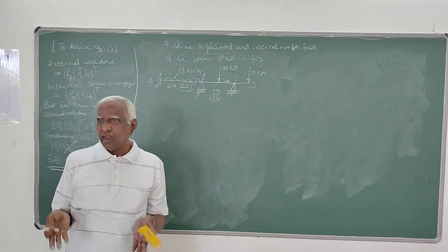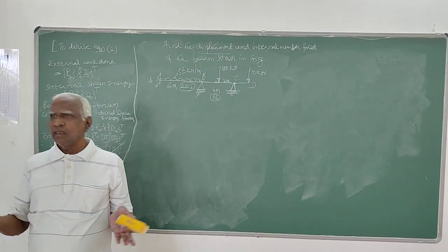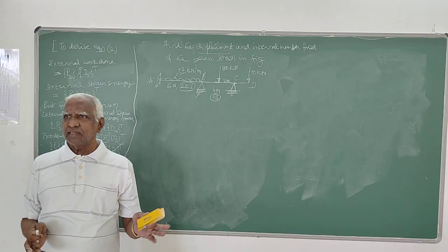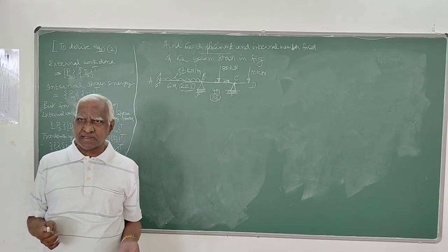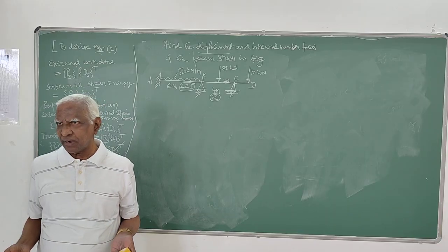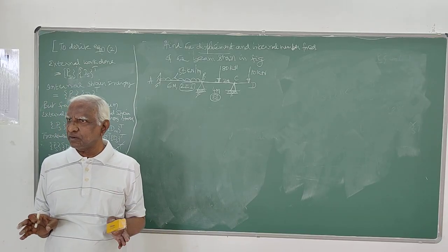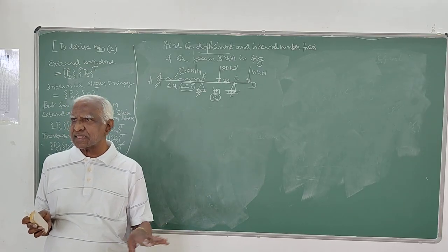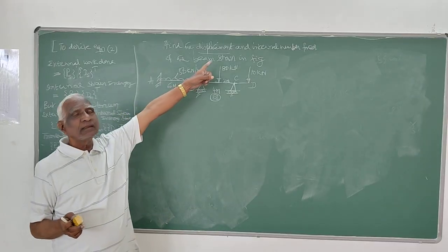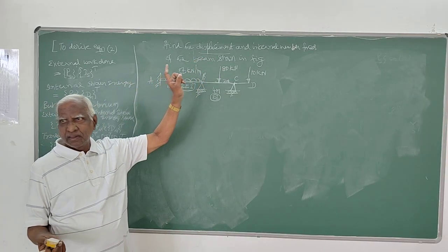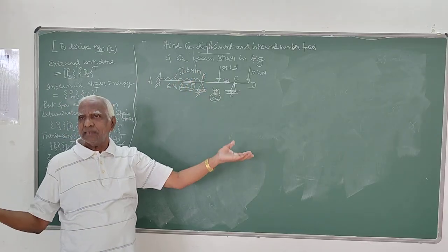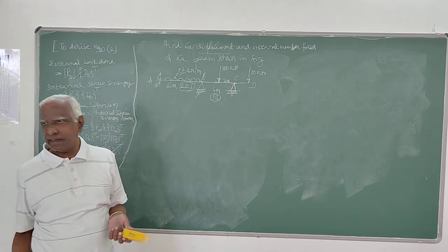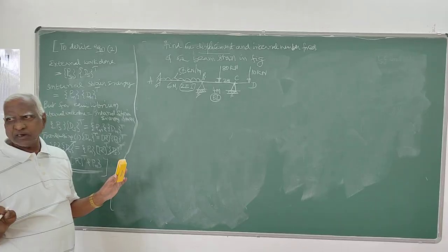That's analysis. Analysis means we have to find the internal forces developed due to external loads as well as the displacements at various points. That's what I told. Of course, support reactions we have to determine. Support reactions as well as internal member forces, that is static indeterminacy. And kinematic indeterminacy is the displacement at various joints. That's what we have to do.